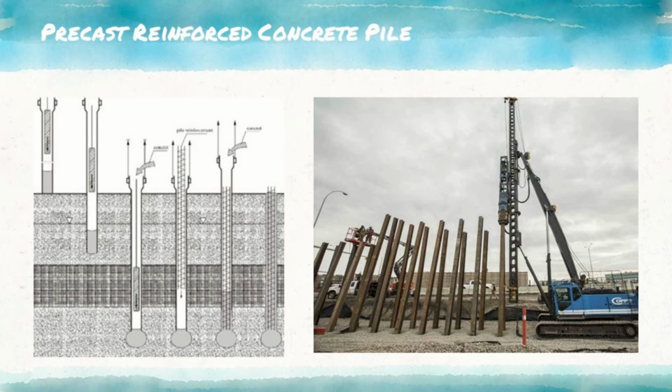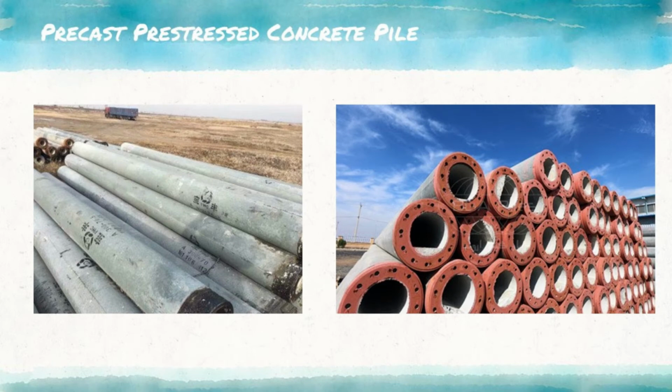Because the weight itself is large, usually these concrete piles are molded and cast at the job site, so they don't bring difficulties for transport. This pile can carry large load more than 50 tons for each pile. It depends on the dimension. 2. Precast pre-stressed concrete pile. Precast pre-stressed concrete pile is a pre-stressed concrete pile using reinforcing steel and wire cables as the pre-stressed force.